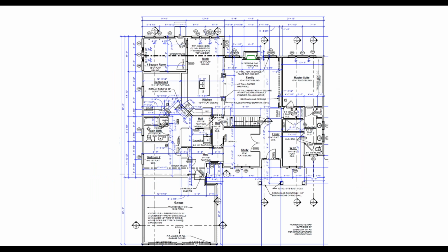The problem is that, or excuse me, I'll get to the problem in a moment. So more of the concept here is that, let's say we're cooking or we're in a shower where we have some aerosolized particulate matter, something like that, and we've got PM2.5 in the house, or perhaps we have humidity in those bathrooms coming in, and maybe we've got formaldehyde throughout the house, off-gassing from different products in the house. Our VOCs from our paints and our carpets and other things are present there in the house, and then we've got something like CO2, which isn't a pollutant per se, but which does have an effect on cognitive function, and you don't want the levels too high.